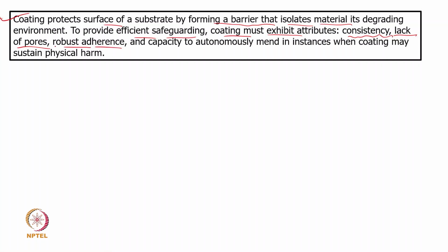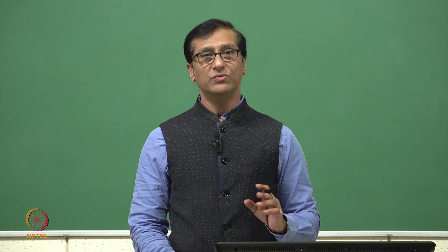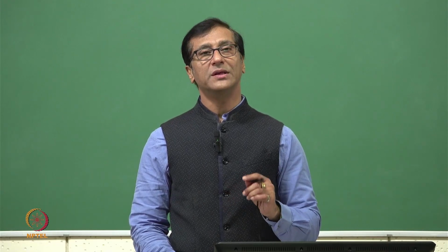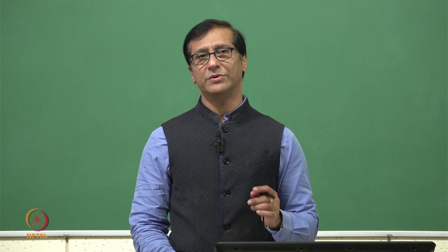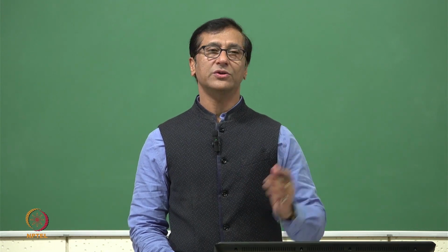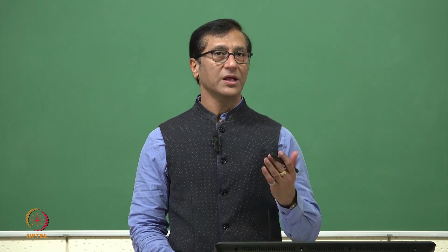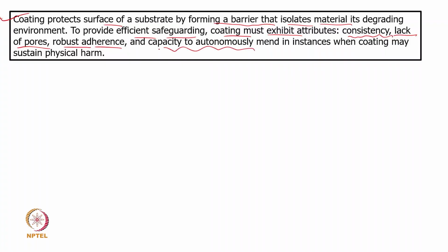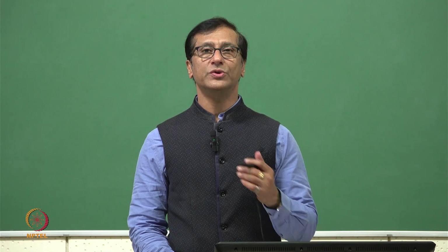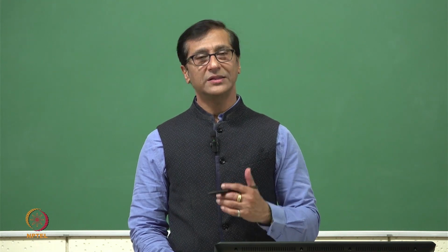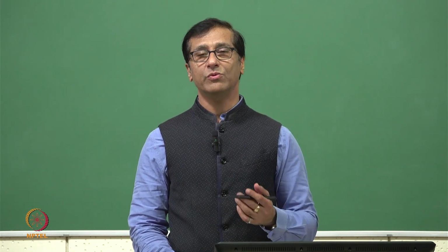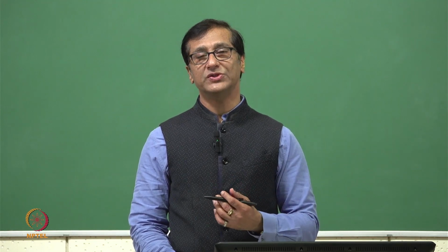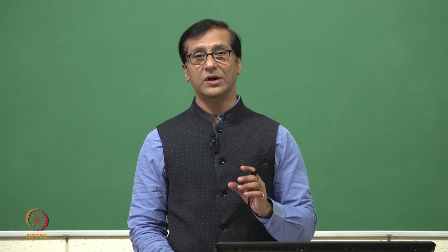Another one is that the coating is not adhering completely, which is a major issue, a major problem, that it doesn't adhere properly because of the manufacturing processes. Then the coating will be removed after some time. Then it is very bad. And the last one, in this case, is that if the coating gets punctured, then it should have an autonomous capacity to repair itself. If not, then continuous monitoring will be required. And as I mentioned in the previous slide, we need synergizing between the liquid lubricant and solid lubricant.